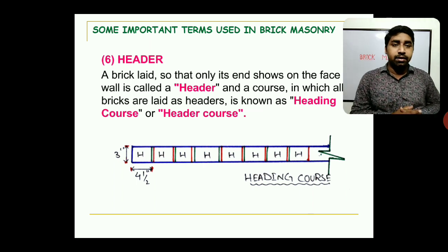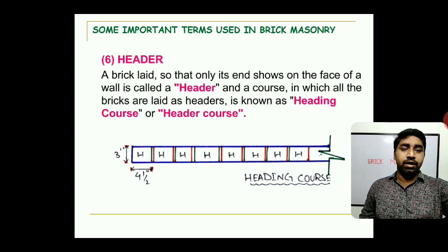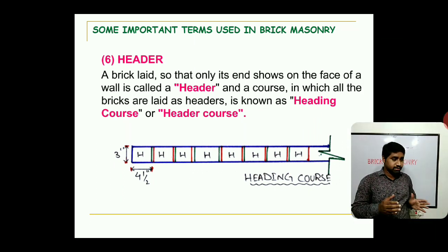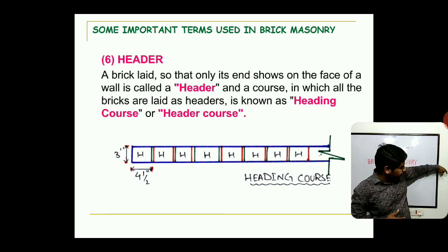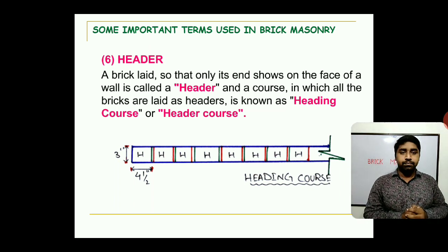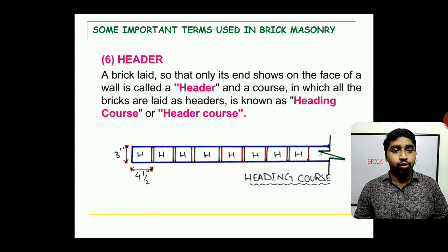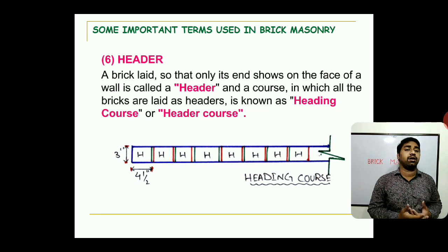So a brick which is laid showing only its end on the face of the wall, that is a header. The brick course which is laid showing all the headers is called a header course.